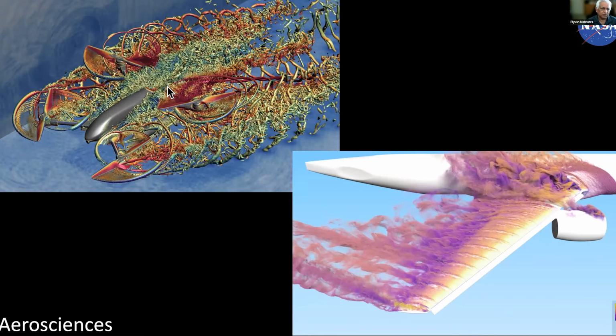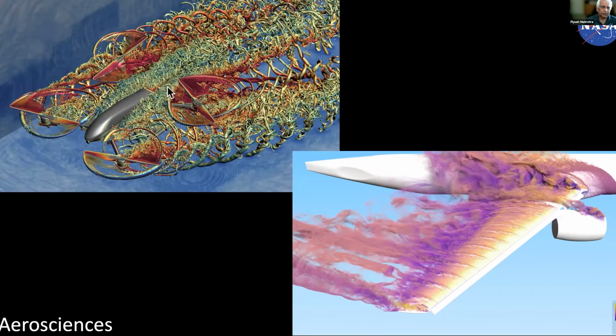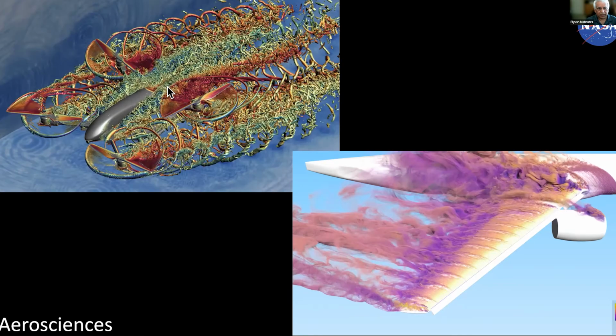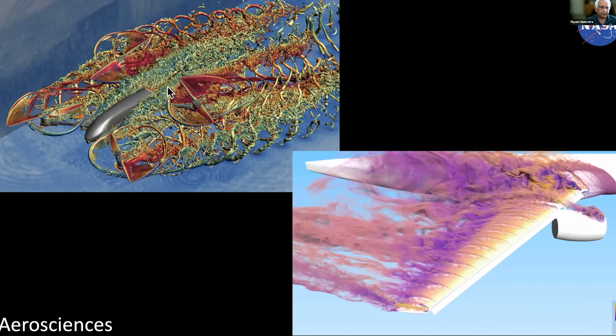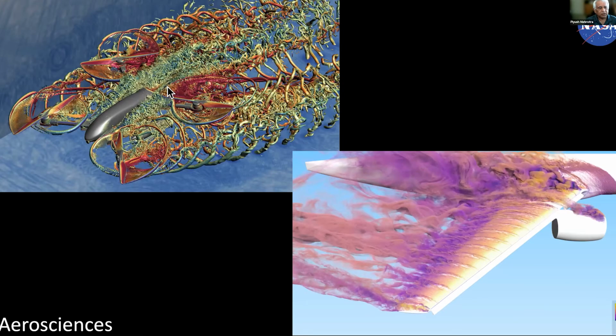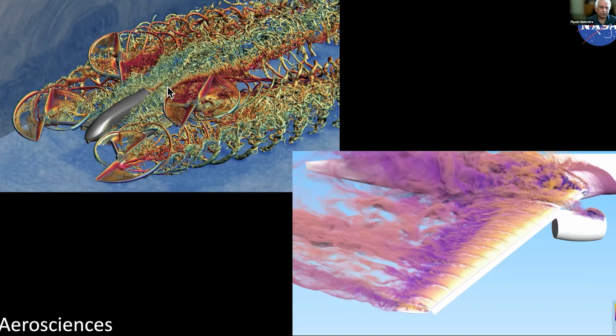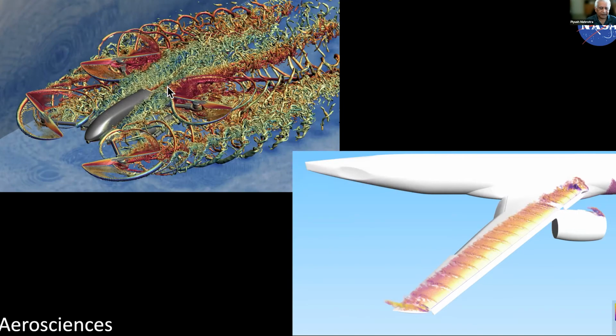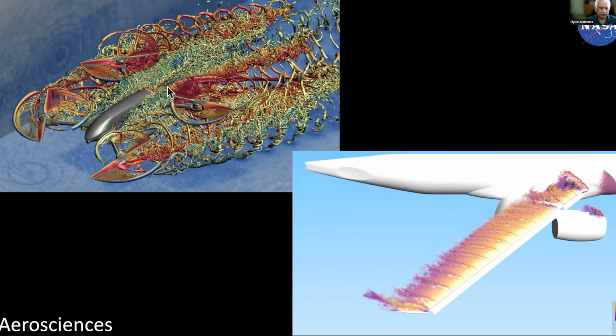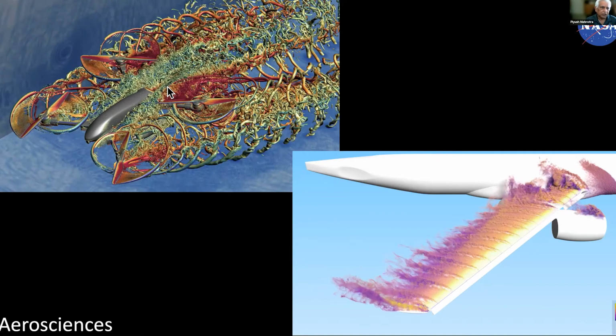So the flow that is produced by the blades in front interacts with the flow which is coming off the blade behind, and causes problems with efficiency and the drag that is caused. And in all the design process, they've been looking at different models where they're putting the blades at the back facing downwards below the copter rather than above the copter. They're also looking, like I said, at the noise issue.